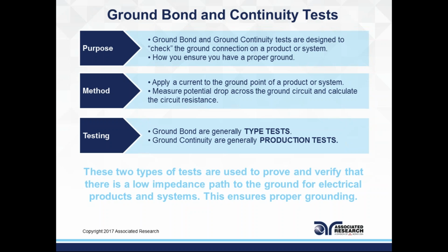But if you provide the layer of protection and you don't test that layer of protection, there could be a miswire where the ground is not connected, and you're still passing out and selling products that are defective in one sense. They also define a proper ground. So we're ensuring a proper ground is in our product before we ship out the product.